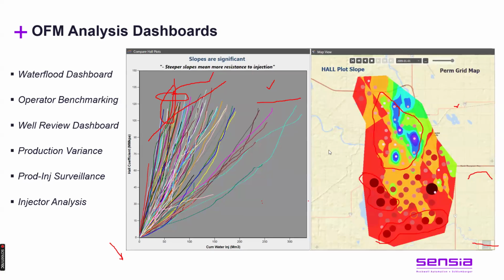So if I bring here a variability map, you can see, yes, here where I have my super K, I'm losing a lot of water. Here where I have a low variability, I have difficulties to inject. This could also be a formation damage index, skin damage. And this skin damage also shows me here, I have a high skin. That's why I can recommend a workover by acidizing, or I can do anything to improve the reservoir quality for my injector. So this is another dashboard, but for the injectors, to show you how you can create and optimize your injection by plotting the whole plot with the dashboard and showing geological data.